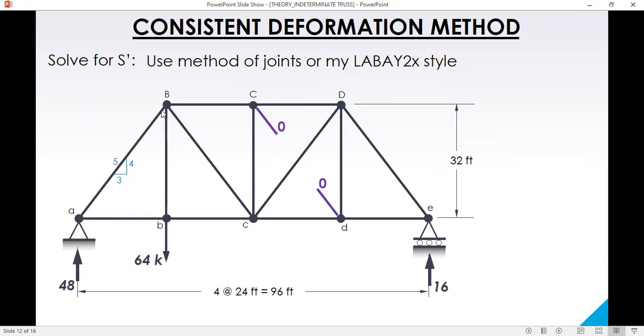Okay. Now, for an inclined member, let's resolve this one into components, horizontal and vertical. So, there are 3 forces: vertical component, horizontal component, and the force of member EB. So we start with one unknown. So we start with the vertical, since for horizontal, there are 2 unknowns.